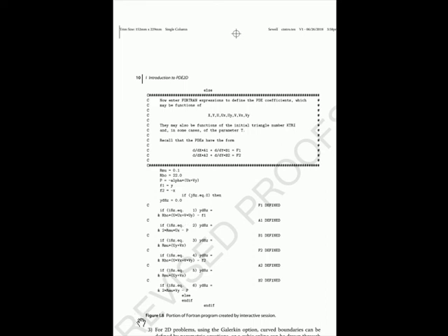Now, for more complicated problems, you are going to have to do a little bit of Fortran programming, but that's what gives it the flexibility. For example, if your F1 here in the partial differential equation was a complicated function that couldn't be defined in a simple expression, suppose it had to go read a file and interpolate, for example. Well, then you're going to have to write a Fortran function that goes and reads the file and interpolates. So for more sophisticated problems, you will have to do a little bit of Fortran programming, but not much.